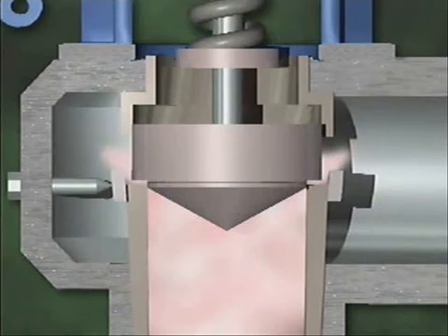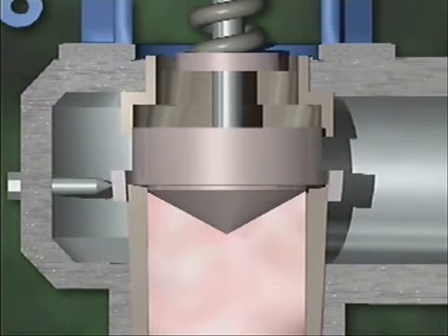The spring tension in a safety valve is preset, and it must be correct for the valve to operate properly. When the system pressure drops to the point where the valve popped open, 1,000 psi in this case, the valve doesn't close, because the lip of the disc is still exposed to the pressure and velocity of the escaping fluid. When the system pressure drops to a predetermined value below the valve's popping pressure, the disc drops down on the seat, closing the valve. This predetermined value is the valve's reseating pressure.